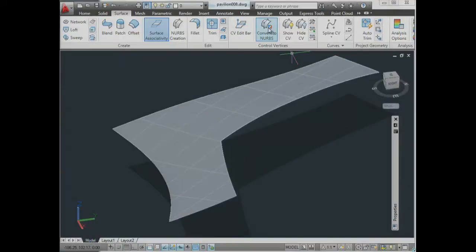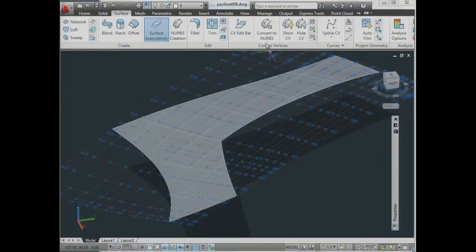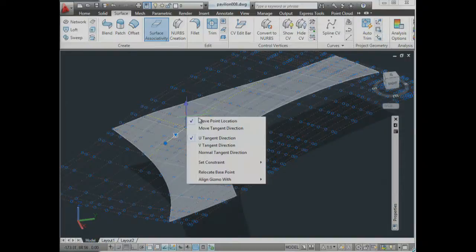One other thing very interesting about NURB surfaces is what you can do with what we call the CV edit bar. Because in the other case, we were just tweaking the hull, which are all those points that you can see now. But we can add more detail to the hull. We can add a row of CVs in any direction. And now what I'm going to do is track any point, which may not be any of the particular points of the hull. I can track that point.